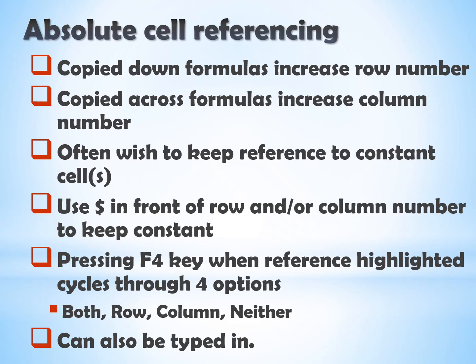The latter action will start a cycle going through 4 options, including freezing both the row and column references, freezing the row reference only, freezing the column reference only, or unfreezing any references.